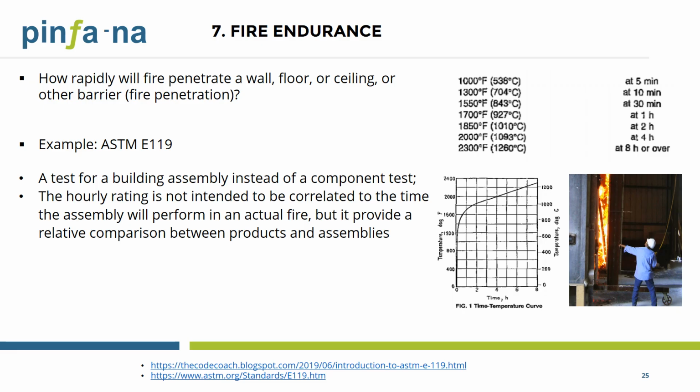Second, the hourly rating is not intended to be correlated to the time the assembly will perform in a real fire because of the wide range of potential fire conditions. But it does provide a relative comparison between the products and assemblies if they are all tested using the same test method.